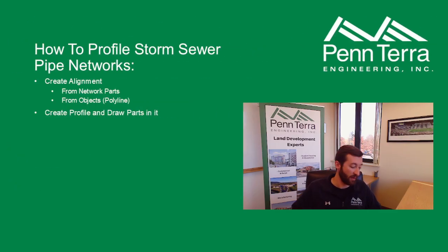Okay, so how to profile pipe networks. The first thing you have to do with any profile is have an alignment. It uses that alignment as the basis to create the profile. We're going to show there are a few ways to create alignments. When we're talking about pipe networks, the most common ways I would do it is either by network parts or from an object being a polyline. After that, we can create the profile based on that alignment and then draw our parts within it.